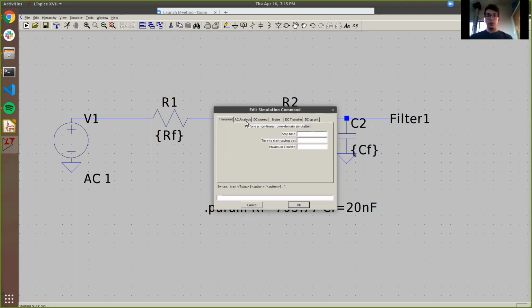So we're going to do AC analysis here. AC analysis just means that we're making a Bode plot. We're looking at the small signal analysis of the filter. So cool. We're going to do a decade, which means every 10th order of magnitude. You probably saw this in ISIM where the x-axis is a log axis where it's orders of 10, and we're going to be doing that type of frequency analysis.